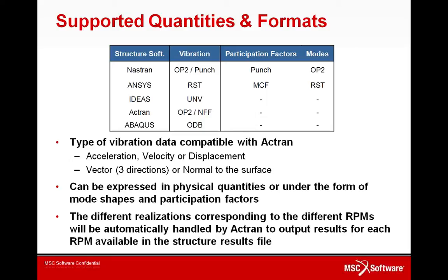And the different subcases present in the Nastran analysis will be treated independently, but simultaneously and automatically thanks to the multiple load case capability. Therefore, the solution will be available for the different RPMs at the end of the computation.